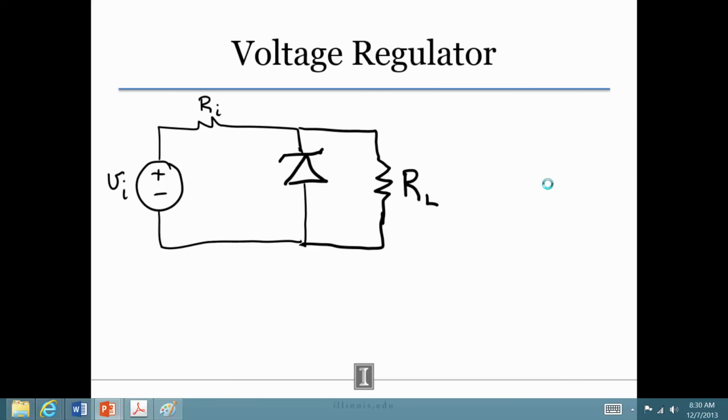Okay, well, the first thing we can do is just simple nodal analysis, right? And what do we do first for nodal analysis? The very first thing we do is set the ground. And I think there is a very obvious node that we can set here. Really, the node is this whole thing, right? But we usually designate it with maybe a big fat dot like this. And we call this VZ because that's the voltage that we want to deliver, right? And that's the operating voltage of the Zener when it is in breakdown. Okay, the reverse bias voltage is VZ.